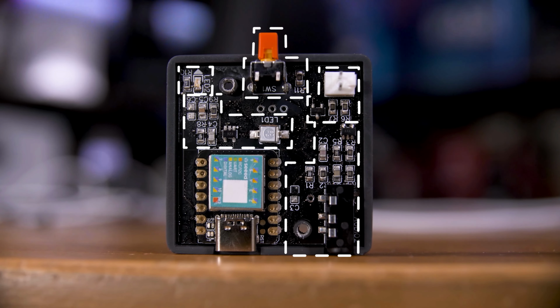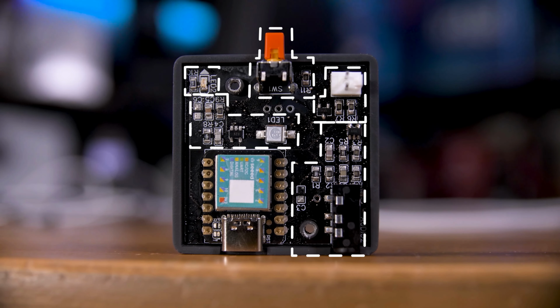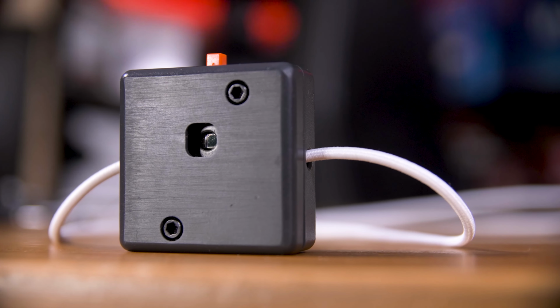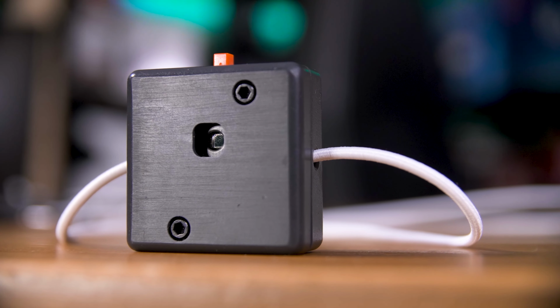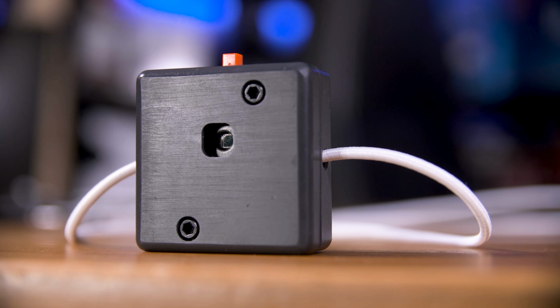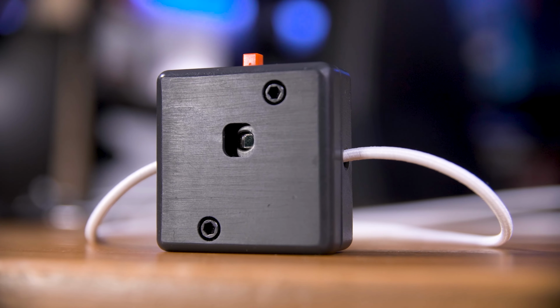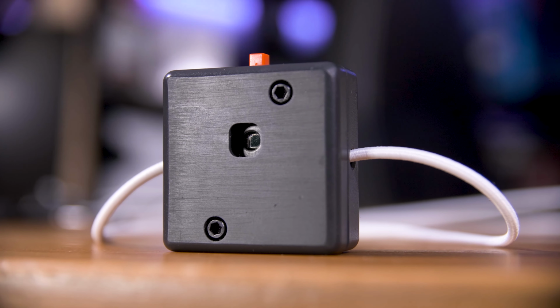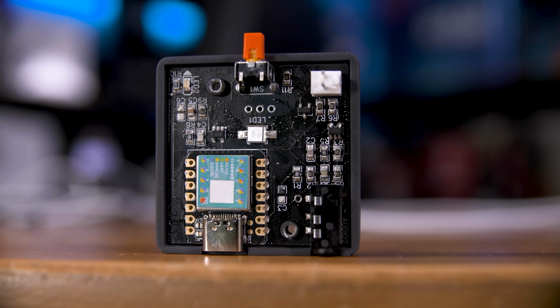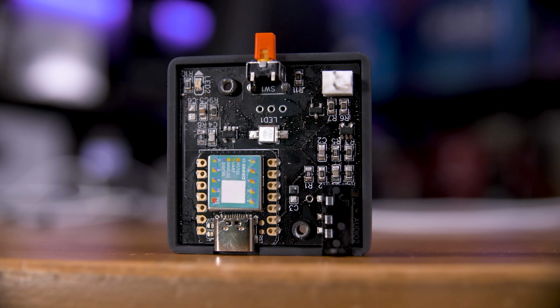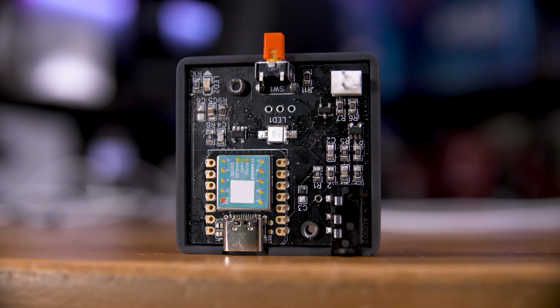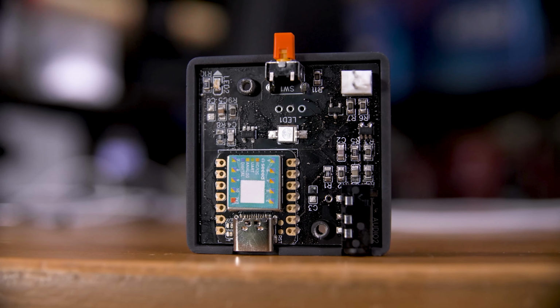The light sensor is pretty much the same as the response time tool, just using a reverse mount photodiode and a cutout through the PCB so that all of the components are on the top, which makes manufacturing easier for me, and I think it's quite cool. It does have a fixed resistance, unlike the response time tools, because you don't care about the granularity, you just care about seeing a light level change.